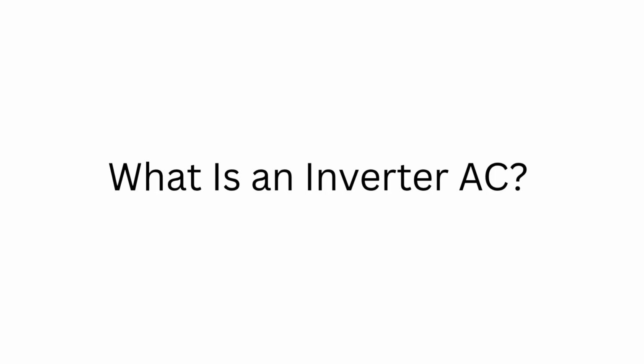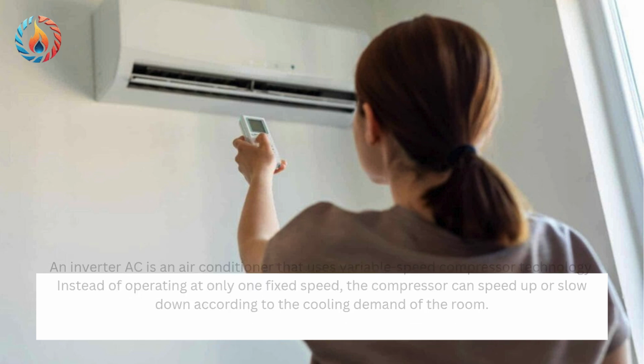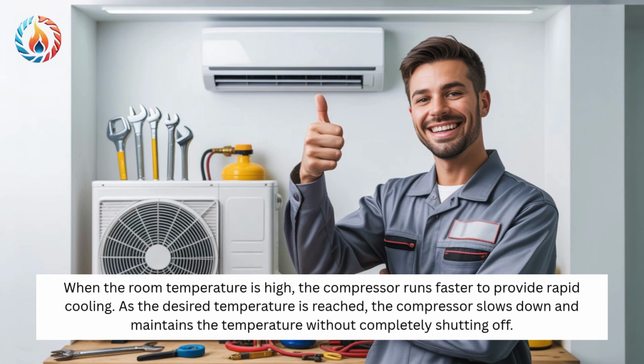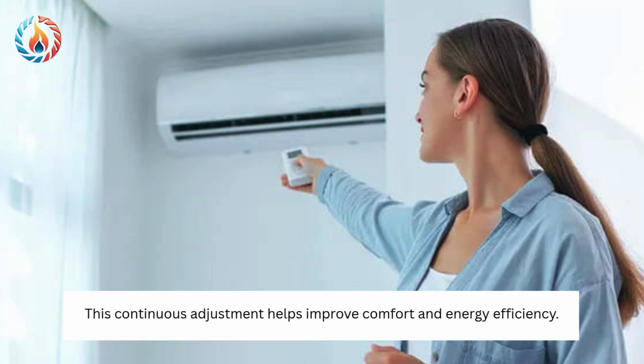What is an inverter AC? An inverter AC is an air conditioner that uses variable speed compressor technology. Instead of operating at only one fixed speed, the compressor can speed up or slow down according to the cooling demand of the room. When the room temperature is high, the compressor runs faster to provide rapid cooling. As the desired temperature is reached, the compressor slows down and maintains the temperature without completely shutting off. This continuous adjustment helps improve comfort and energy efficiency.